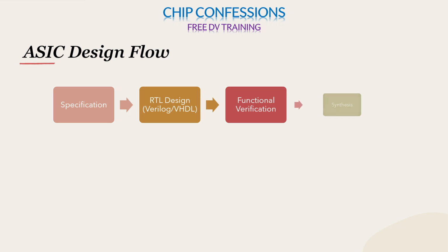Later on, after this functional verification, what we are seeing is the synthesis. In this synthesis, once the verification is done and the design is frozen, what we are doing is converting the design into a gate level netlist, and everything will be represented in terms of logic gates.